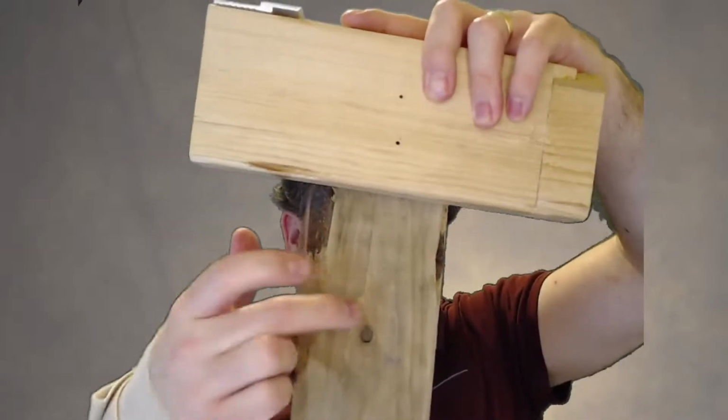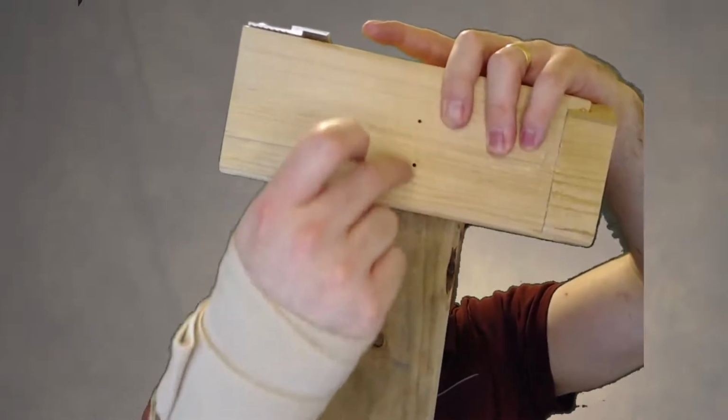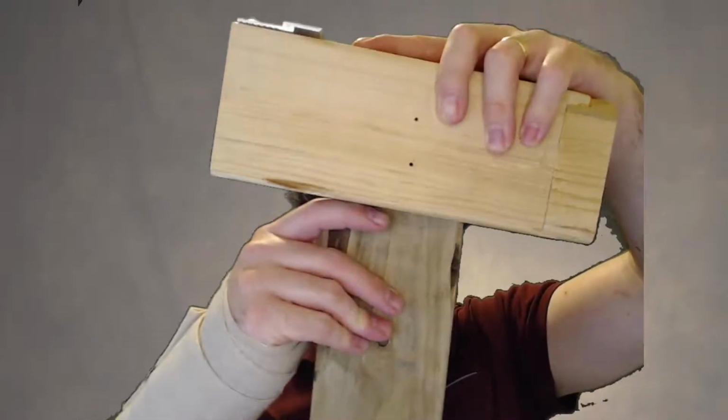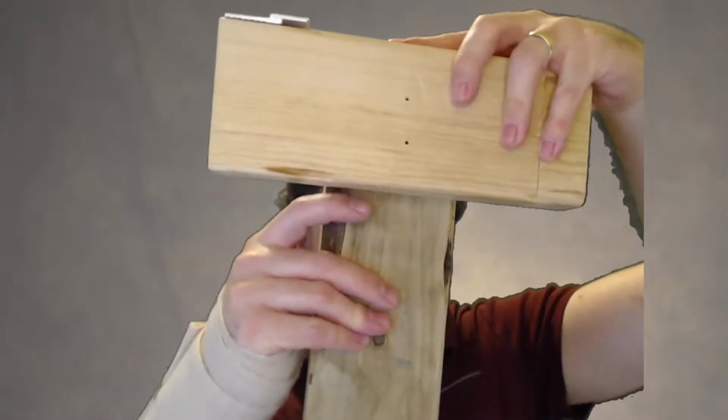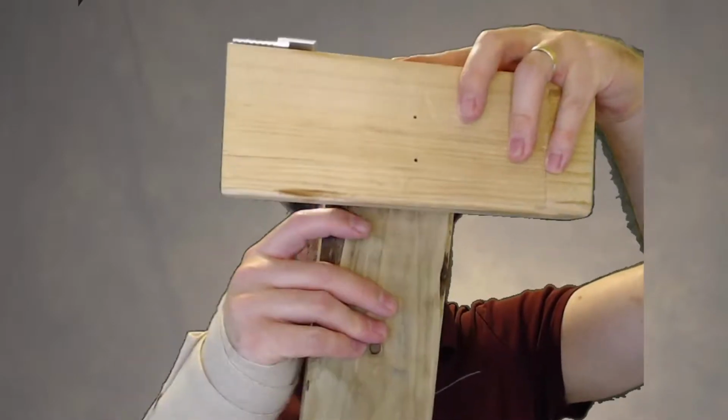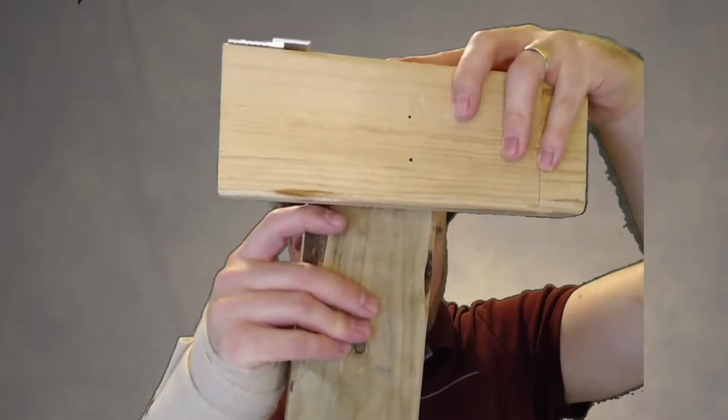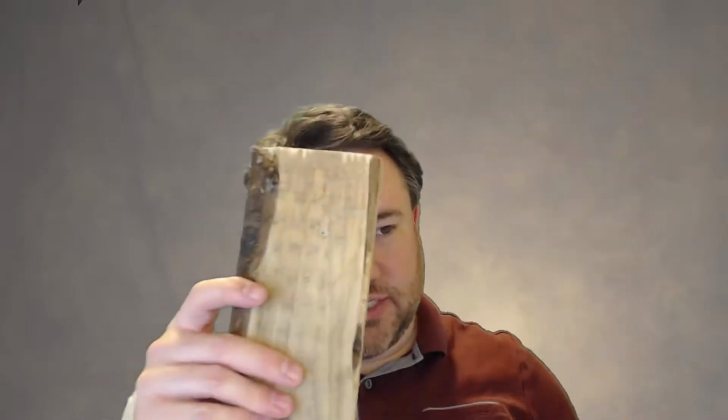Now, what about for this member here? This member is connected with 2 bolts, for example, and when this member pulls down, the bolts are going to want to stay there, and the bolts are going to pull up in this member, right? They're going to want to pull up. So as this member pulls down, the bolts in that member, which are restrained by this one, are going to want to go up towards the end of this member.